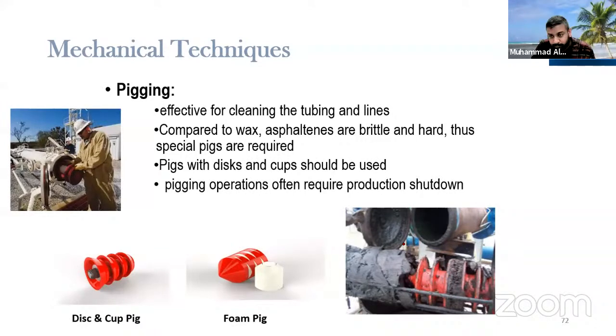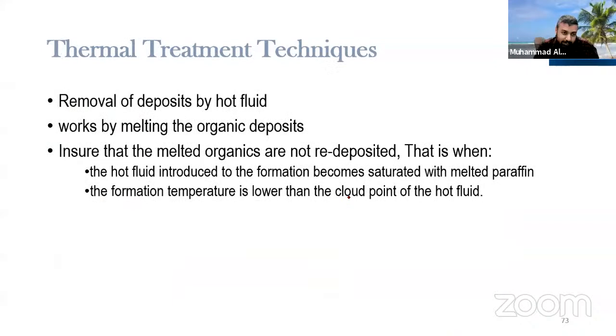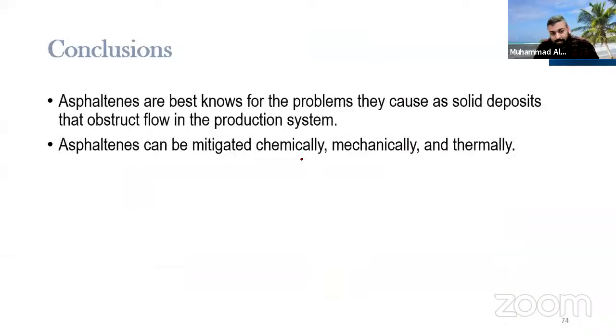Yes, tubing has problems. So what we can do is clean it with these inhibitors and keep it dispersed. We also have to use scratchers again. Yes, sometimes we have to use mechanical equipment to keep it clean, because this is the well intervention engineer's job, to clean up the production tubing and so on. So here is one of the jobs. Another research topic here could be how we can avoid the shutdown operations and still manage the asphaltene. And then of course, we can heat up the pipeline to remove deposits and so on.